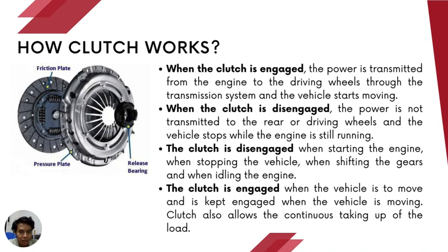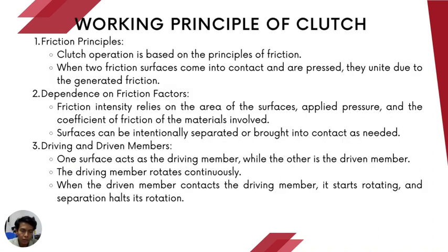The clutch is disengaged when starting the engine, when stopping the vehicle, when shifting the gears, and when idling the engine. The clutch is engaged when the vehicle is to move and is kept engaged when the vehicle is moving. Clutch also allows the continuous taking up of the load.